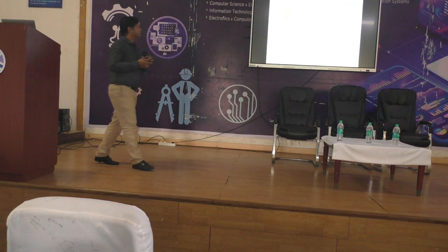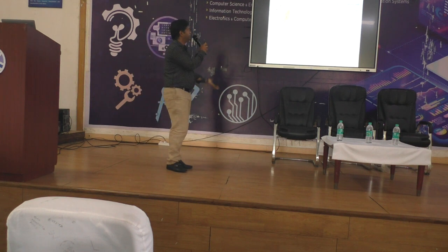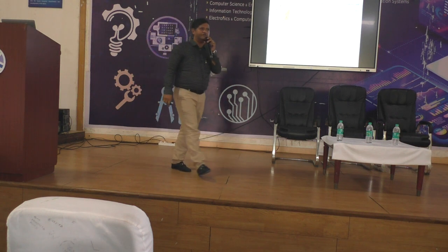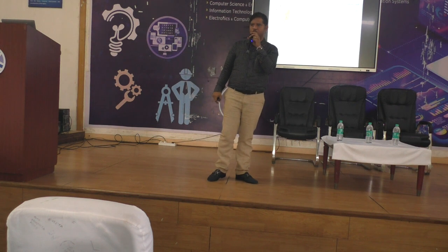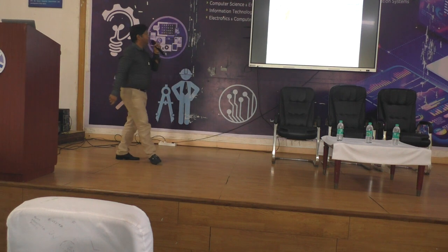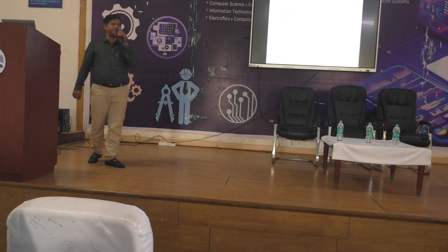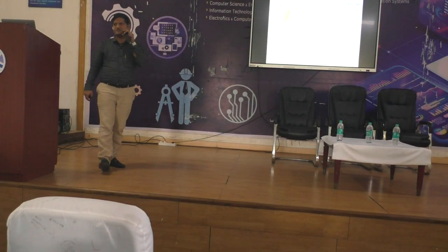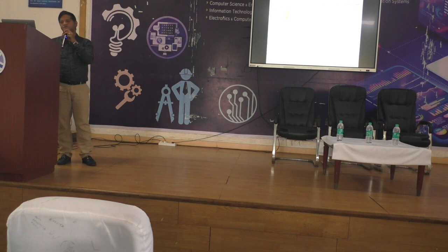The tooling and fixturing costs are substantial for low volume production. In the sense, if you go with conventional manufacturing for low volume production, the tooling cost will increase significantly, and the cost of the product will increase significantly. At the same time, the lead times will increase if you go with conventional manufacturing for product development. Examples of products falling within this region are the functional prototypes, which we use for testing before going for conventional manufacturing for high volume production.